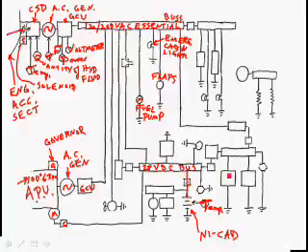Also, if we want to run our engine gauges or our avionics on the ground, we could close this contactor as well as the contactor. Essentially, this contactor is run by the electrical master switch, or the battery master, that connects the positive side of the battery to this bus bar.